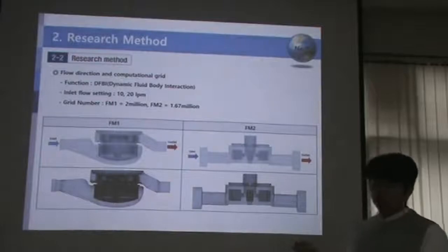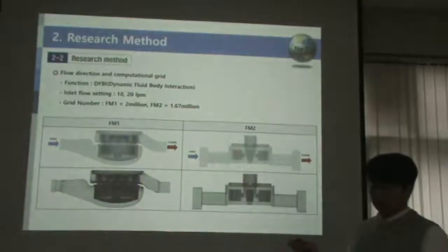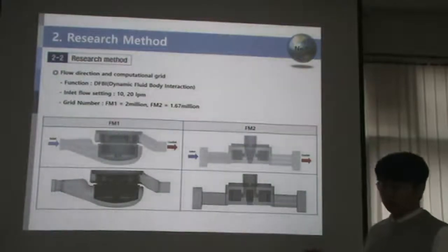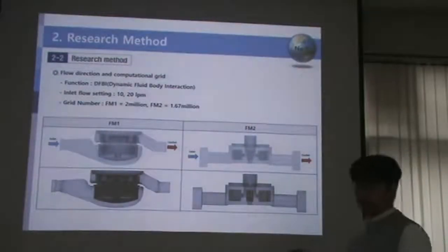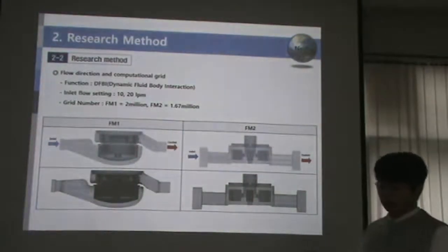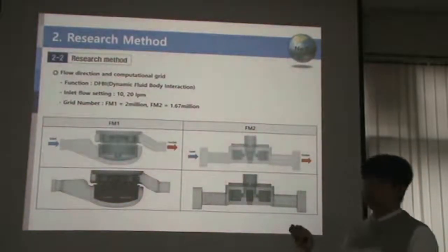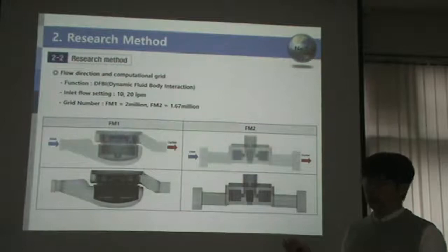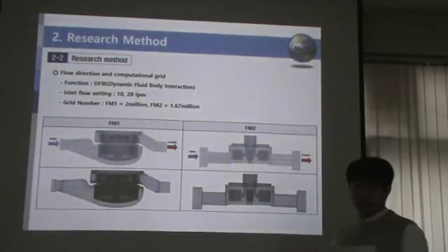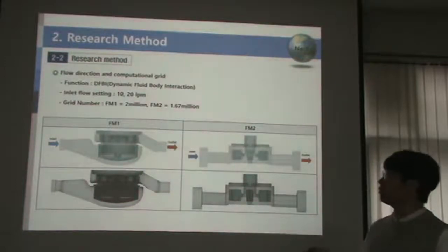In the study, flow analysis was performed using STAR-CCM+ commercial software. The flow analysis of the water meter assumes unsteady turbulent flow, and the turbulence model for the flow analysis uses the standard K epsilon turbulence model. The fluid used in the flow analysis was water.